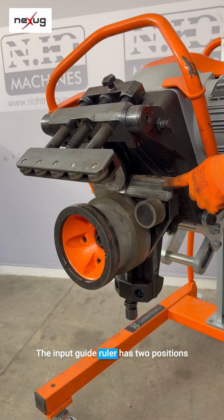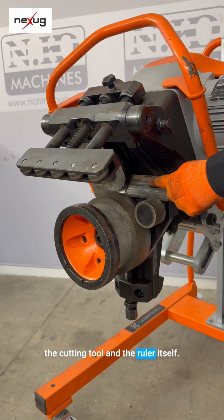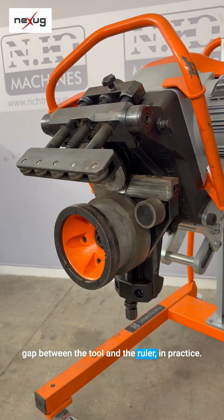The input guide ruler has two positions that adjust the distance between the cutting tool and the ruler itself. In general, the thicker the material, the larger the gap between the tool and the ruler. If for any reason the machine's feed along the material is not smooth and the machine binds on the material, one possible reason may be an incorrect position of the guiding ruler. The correct ruler alignment also influences the tool's overall lifespan.